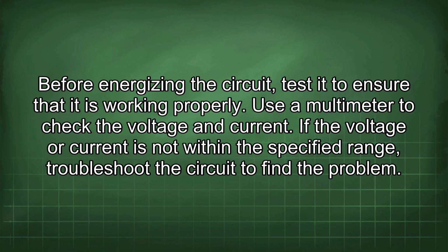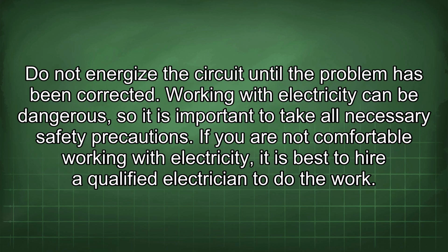Before energizing the circuit, test it to ensure that it is working properly. Use a multimeter to check the voltage and current. If the voltage or current is not within the specified range, troubleshoot the circuit to find the problem. Do not energize the circuit until the problem has been corrected.